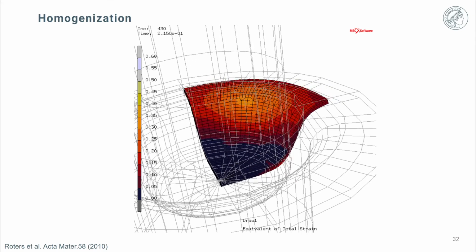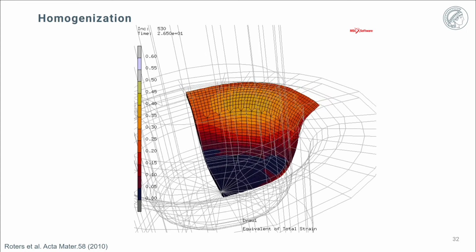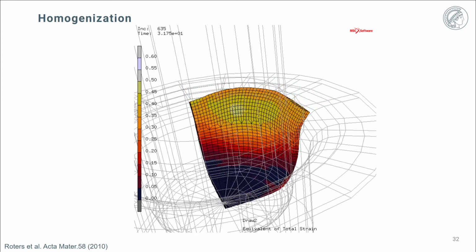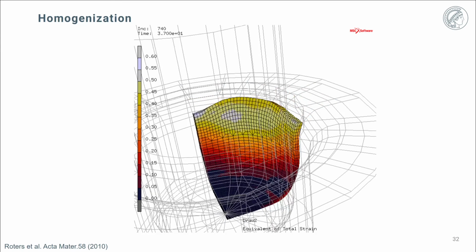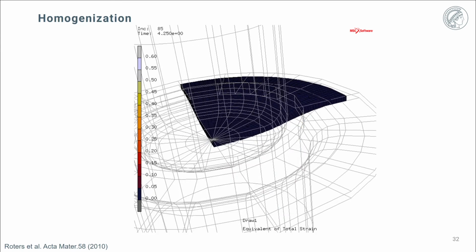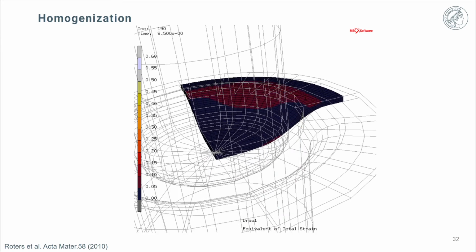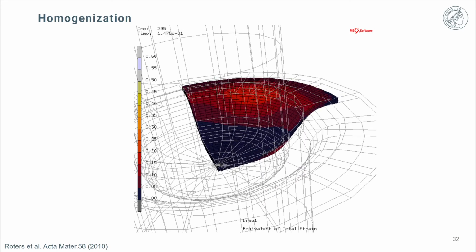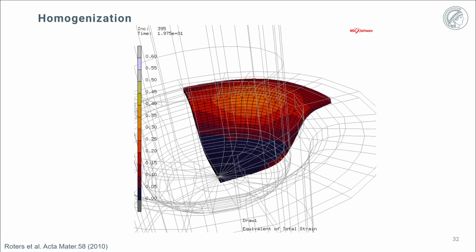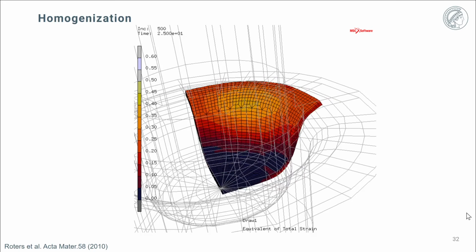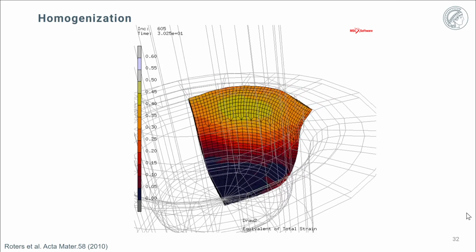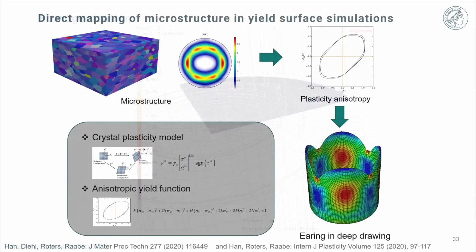These homogenization methods can be picked from the DAMASK solution, and they can be isostress, isostrain, or more complex Taylor type of models or self-consistent type of models that are behind the local representation of the stress feedback at each of these integration points, representing the local microstructure behavior.